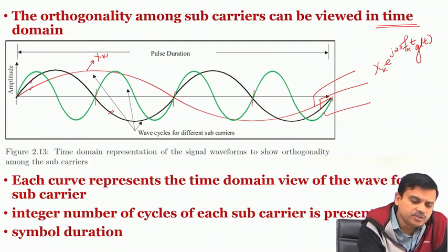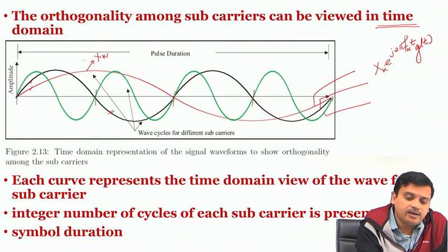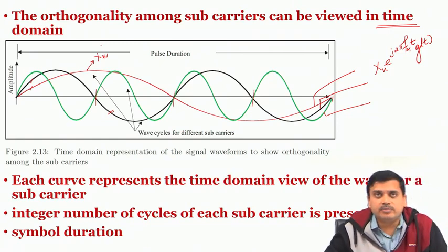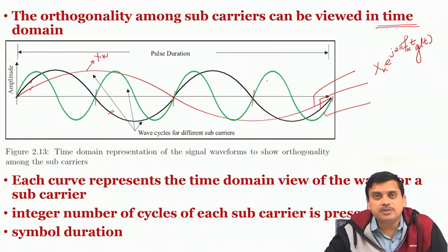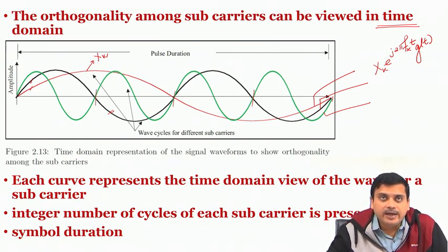The phase term is going to simply change the starting point, and the amplitude factor will simply change the amplitude. What we see over here is that all of them have the same amplitude. So, this could indicate the choice of a PSK kind of a structure or a QPSK kind of a structure that could be imagined to be associated with this particular waveform.